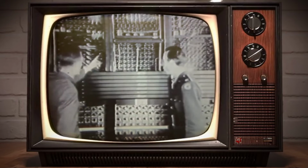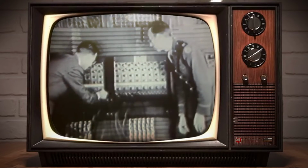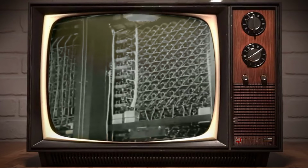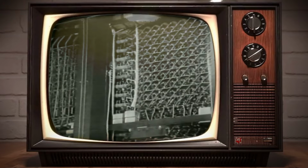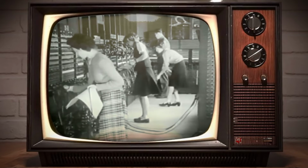I'm on the left and Herman Goldstein is on the right, in front of the 3 racks of the high-speed multiplier. From the top down, you see wiring, the digit trunk, the control panels, and the program trunk. The diagonal lines are the outputs of the shifter circuits. For each successive digit of the multiplier, the partial products were shifted one more position to the left. After the program was worked out on paper, it took a couple of days to set up the machine.